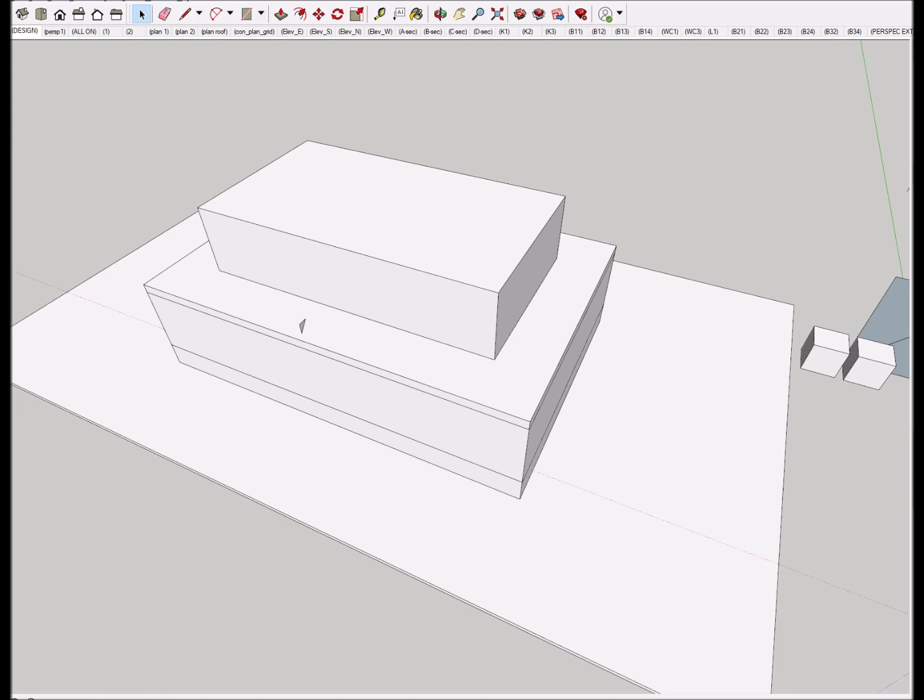Now that's an 8-foot ceiling, and those rooms upstairs are going to be bedrooms. They can have lower sections of ceiling than that, so eventually it'll come out a little more. But those will be sloped ceilings, and they'll come down. I have found that generally a 5-foot wall height works pretty well for an attic bedroom. You can put the headboard of a bed up against the wall, and you can sit up in bed without a problem. So 5 feet works nicely. It's also okay for the back wall of a closet. Occasionally I'll go down to 4 feet, if it's a small room, like a small child's bedroom. So those are just some ideas on attic bedrooms.